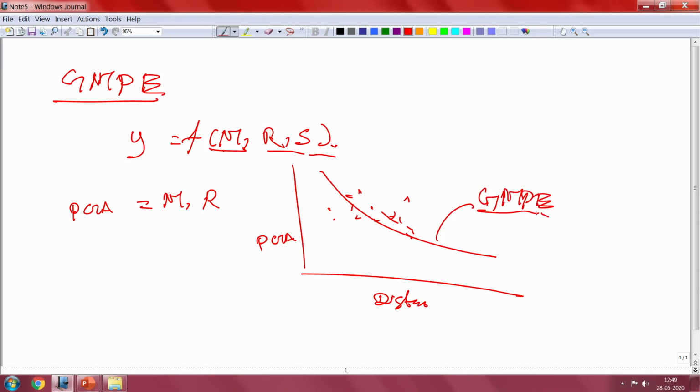So from the parameters we have seen, you can estimate the time domain parameters: peak velocity, peak acceleration, peak displacement, and duration values, which are a function of how many cycles repeat in the record as well as the strength or energy of the earthquake. Using these two you can get predictive models. These predictive models help you arrive at the expected value in the future for an unknown magnitude and distance. That is what they can do.